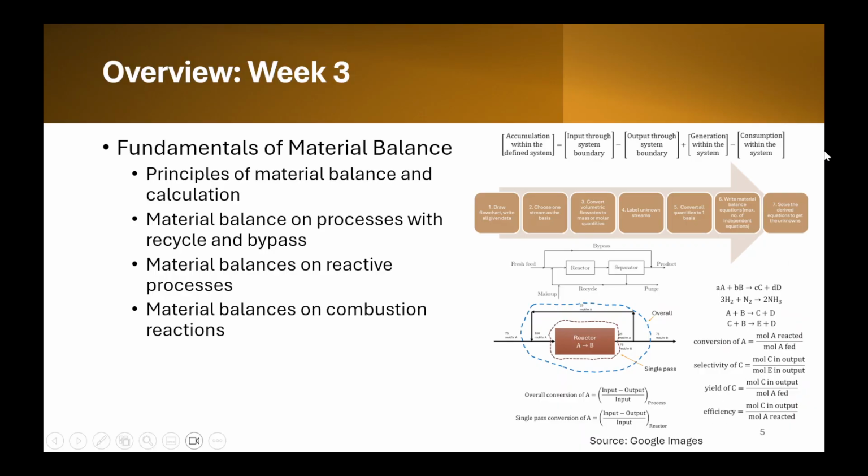So it discussed the fundamentals of material balance. Firstly, we started with the principles of material balance and calculation. So we saw the general material balance equation given here. Accumulation within this defined system. So you basically define a system. Anything coming in, anything going out, anything accumulating inside it. If there's a reaction, anything being generated or anything being consumed.